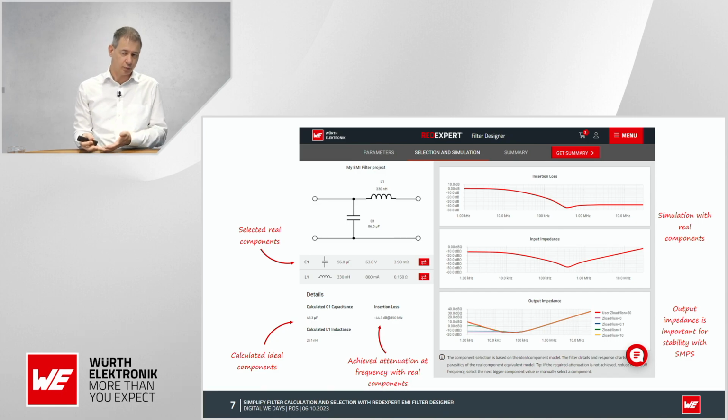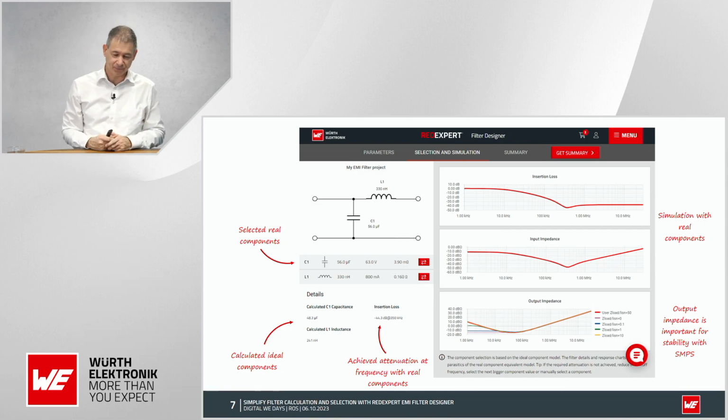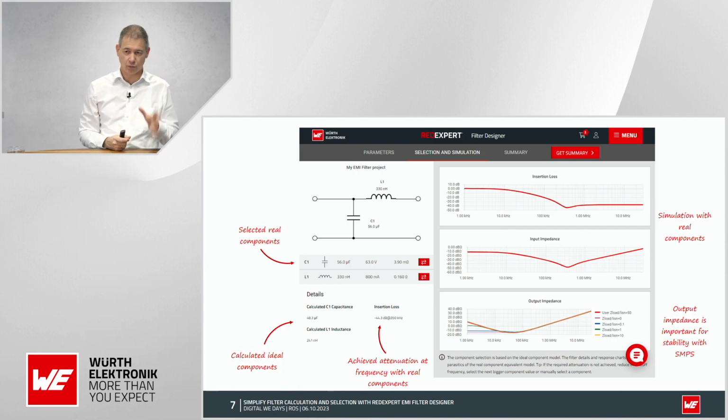That's the first point to see it. Another point is to build the electronics and make a Bode plot or a step response measurement. Those are the possibilities. But always, if you insert frequency dependent components for filtering in a switch mode power supply design, please check the stability.